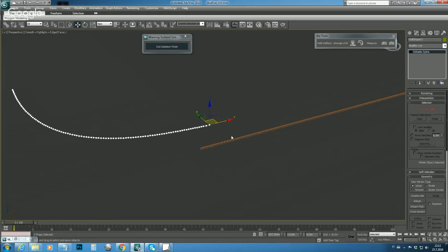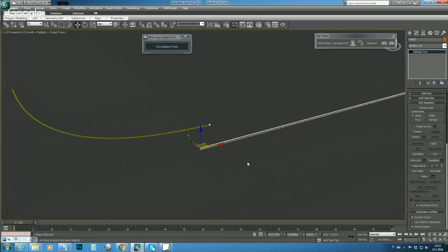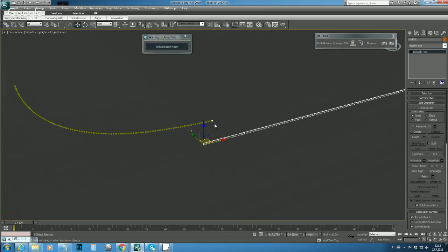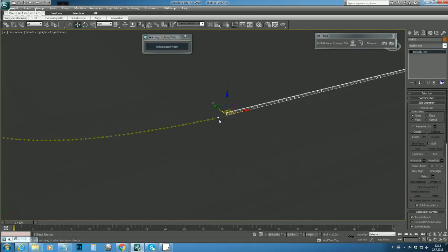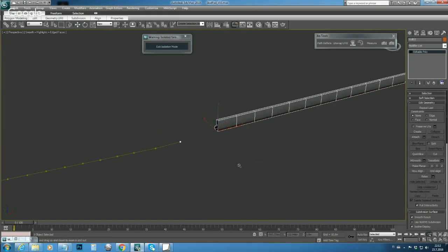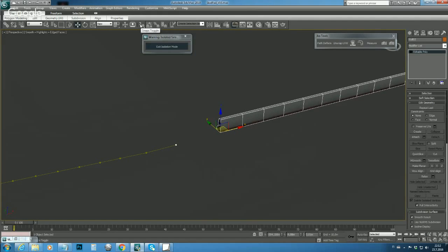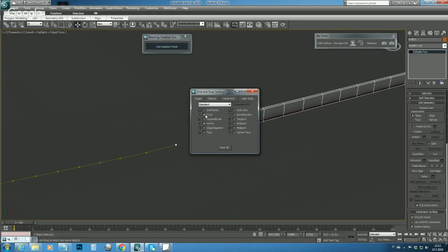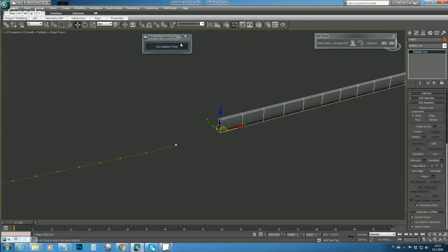And what we need to do next is to snap this wall to the first vert and the pivot point of that spline. And I use the pivot snap again, so I bring up the snap tool, activate it. Again, go near to the wall.